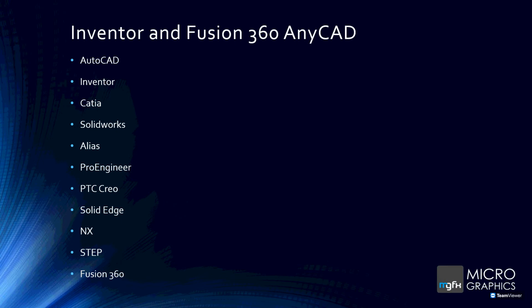You can do AutoCAD, Inventor, CATIA, SolidWorks, Alias, Pro Engineer, PTC Creo, Solid Edge, NX Step, and Fusion 360. Okay, so when I say AnyCAD, let me just explain that to you. AnyCAD is kind of like, if you've worked on AutoCAD, your XREFs. So if I create a model and I send it to you, and then you've got Inventor, and you want to AnyCAD my file, any of those files that are currently sitting on the screen at the moment, into my Inventor model, it makes it like a reference.